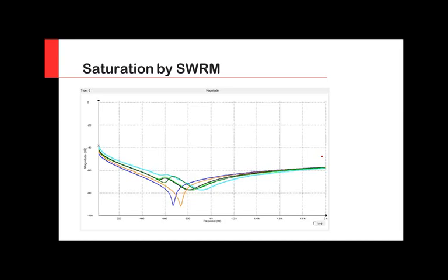To make it a little bit more clear for you and to expand a little bit the visual effect, you can see now that the frequency response here is not on the logarithmic scale, but on the linear scale. And we're looking only between 20 hertz and 2 kilohertz, where the influence of the magnetic core of the transformer is.